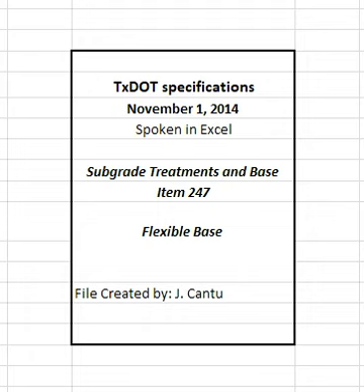Certify compliance with DMS 11000, evaluating and using non-hazardous recyclable materials guidelines, for contractor furnished recycled materials. In addition, recycled materials must be free from reinforcing steel and other objectionable material and have at most 1.5% deleterious material when tested in accordance with TEX 413A.